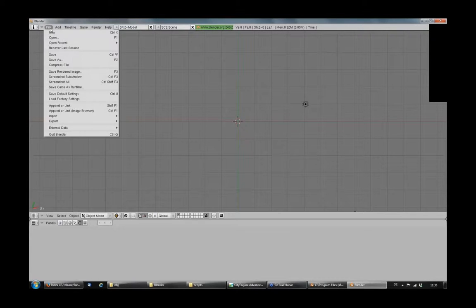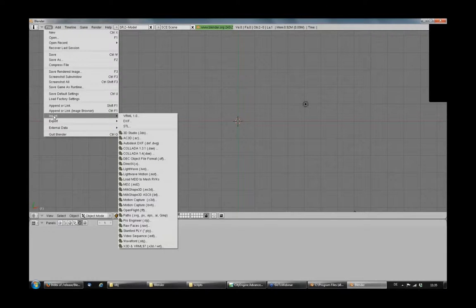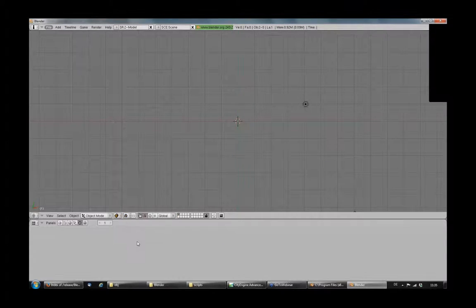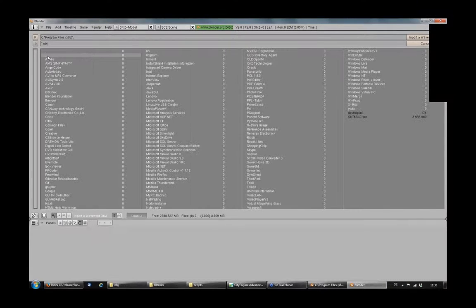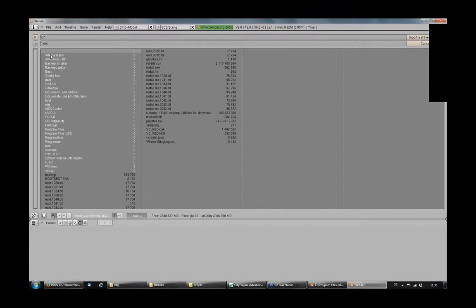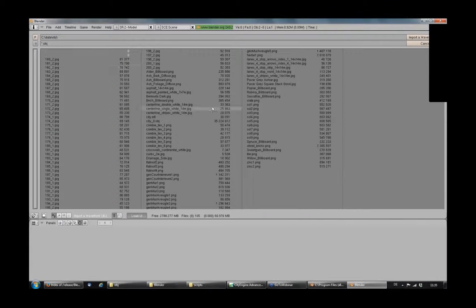Okay, first thing we have to do, we have to open the OBJ file we just created with Blender. So we don't use open here. Instead of this, we go to import and we select the Wavefront OBJ from here. Now we go to the exact path where we stored it. This was at data OBJ, and we look out for the city_0 OBJ file. So after I've selected this one, I click here on import Wavefront OBJ.